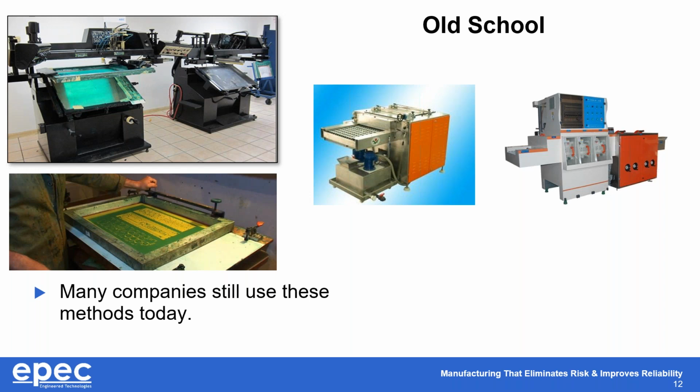And that's typically sometimes used in old school processes to try to flatten out the process after you put the vias or you fill the vias with any type of conductive or non-conductive paste. Or the one on the right is an old school deburring mechanism, right? Whenever you're coming out of drill, and you have burrs from driving the drill bit through the copper, that particular piece of equipment is used to get those burrs off of drill panels.